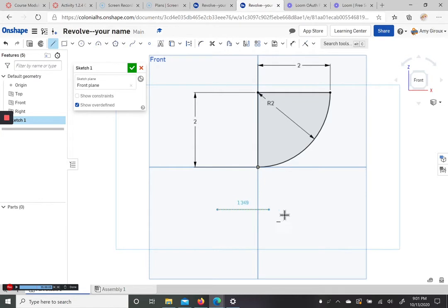But before we actually go do that, we want to add one more line for this object, just somewhere down on the bottom here. If we want it to be horizontal, it'll snap and show that dotted line for a moment. That's what we're going for. If you see, there's a little horizontal line down to the right of my cursor. That's showing that automatically it is using the horizontal constraint, which we'll talk more about a little later.